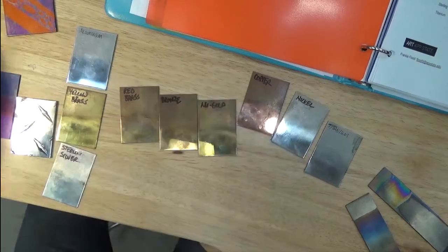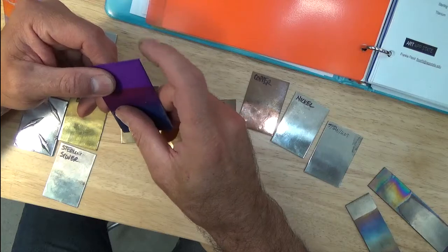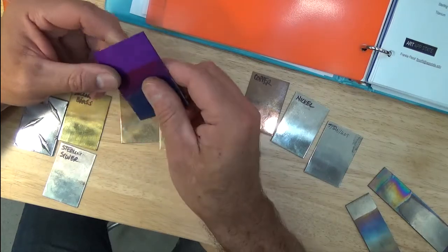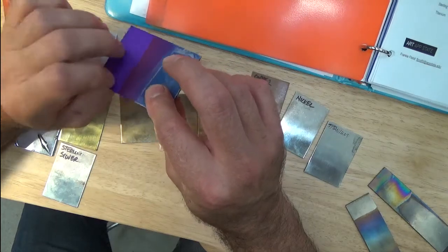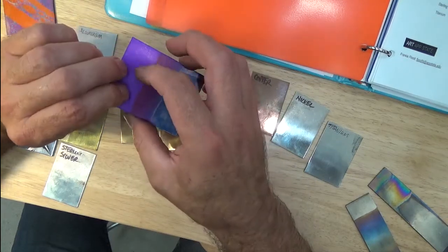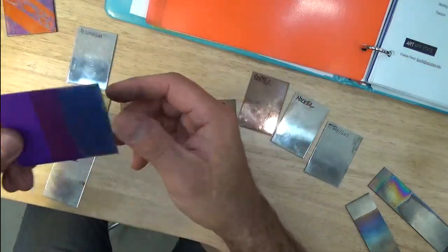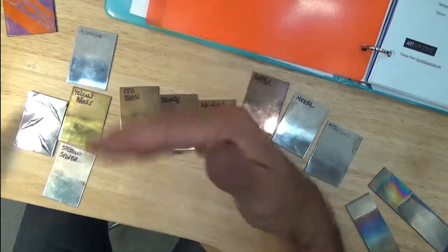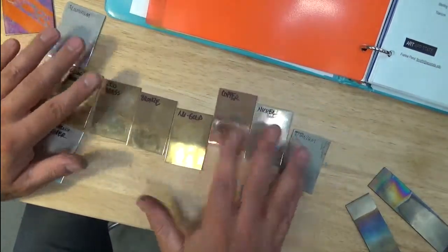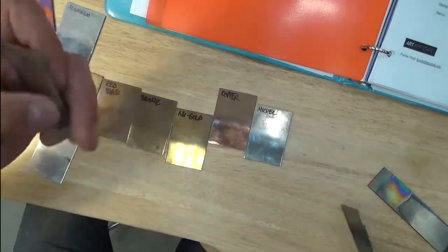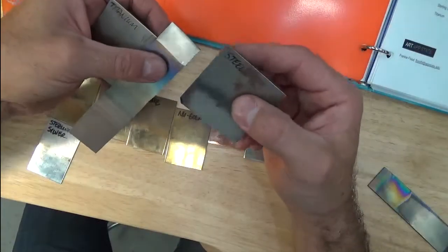So none of these will, except when aluminum has been anodized, it will initially throw a spark as it grinds through that hard layer, because the anodizing actually hardens the metal and makes it resistant to coloring. So that one might spark a little bit in the beginning, but once you break through that surface, it will stop sparking. But the rest of these will not throw a spark. But titanium and steel both will throw a spark.